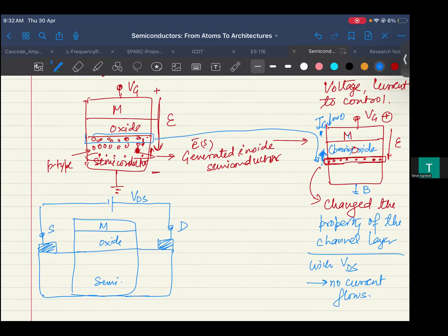So then it becomes very important to see how you can tune this, because you see the p-type semiconductor, right? So if this was p-type and you, let's say, dope these two parts p-type as well, then even if you don't apply any gate voltage, zero gate voltage, because it's p-type, there is no barrier you are going to feel. So the hole is going to have a free ride. If you apply an electric field in whatever direction, let's say like this, the hole is going to feel a free ride.